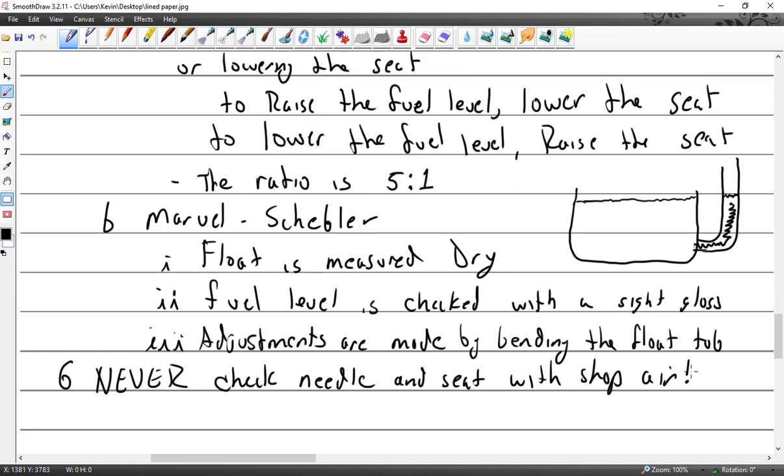And I'm very busy doing something, and they've been working on it all day or something. It's like, what do you think it could be? And I'm like, well, it sounds like it's running out of fuel. I don't know. I mean, is the float bowl filling up, and then you're starting it, and then the float bowl is being drained out, and no fuel is getting back in?